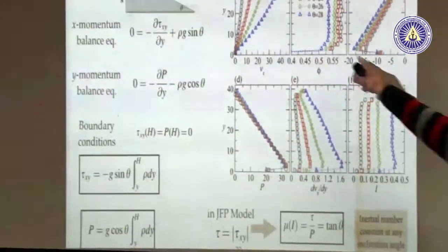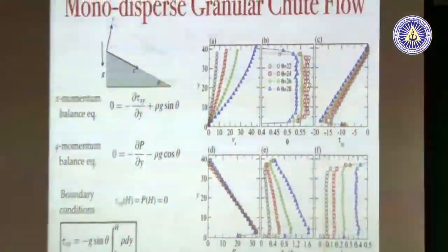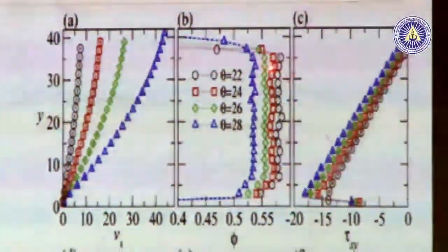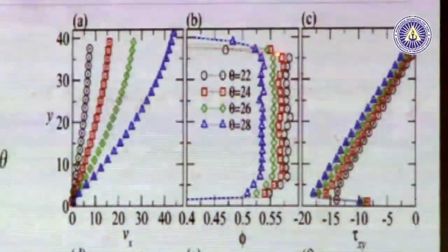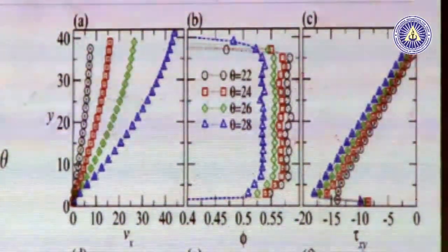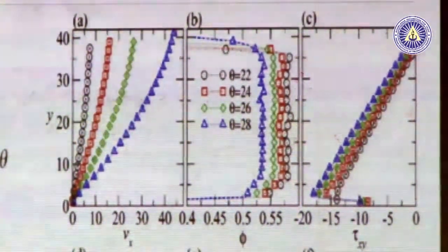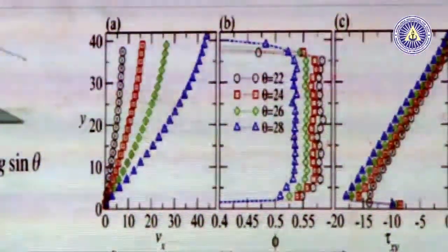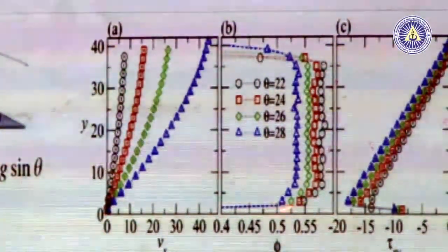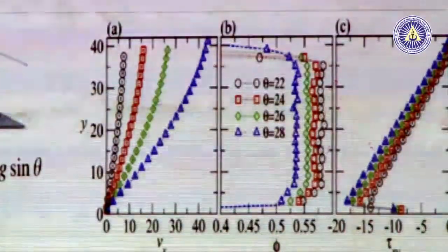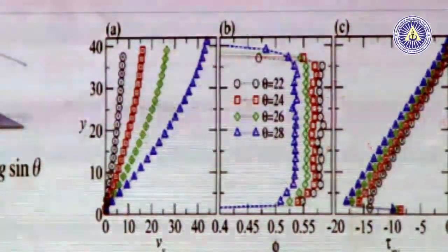Well, it breaks down when your packing fraction starts to deviate significantly. For this case, for example, if you look at the packing fraction, you have more or less constant packing fraction all the way here, and then it starts to decrease here. So the packing fraction suddenly starts to change, and that's how you identify the free surface region. So you have a free surface region, then a bulk region in which packing density doesn't really change much, and then a base region where again something is happening.